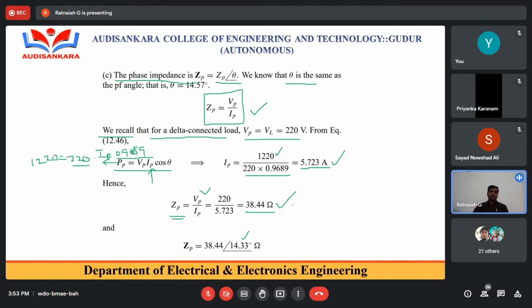This is only the magnitude. How to calculate the phase angle? The per phase impedance of any three-phase system is always in terms of either rectangular form or polar form. If you want to represent it in polar form, definitely we require magnitude as well as phase angle. Therefore, Zp has magnitude 38.44 ohms and its phase angle is 14.33 degrees.